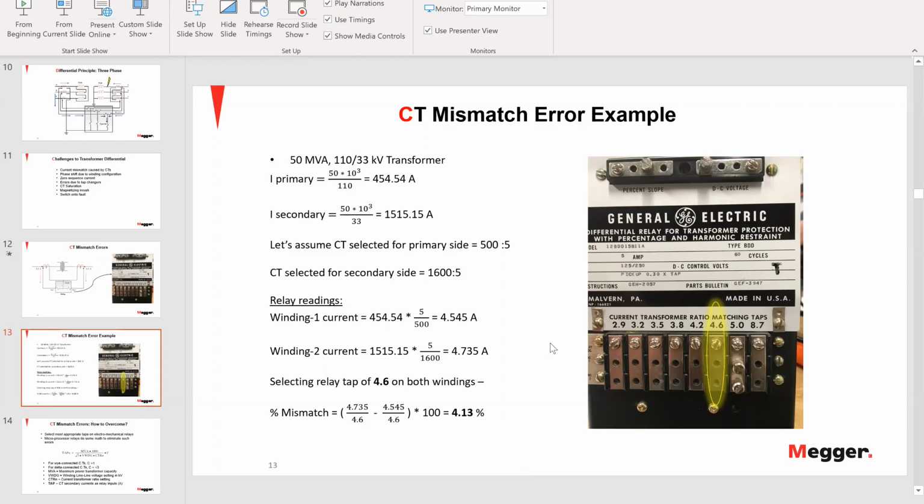So once you get into the test module for the SEL787, that test will automatically adapt to the 410, and you'll use the 6 dedicated currents if it's a 5-channel box, and it'll automatically detect that, and then you can run your test with that. If it's going with an SMRT 46, then the 3 voltage channels will be converted to current channels to perform the same test.